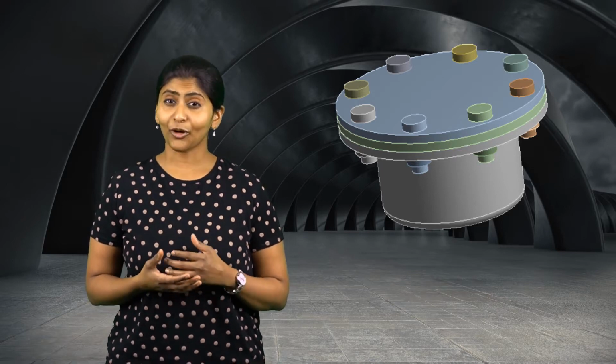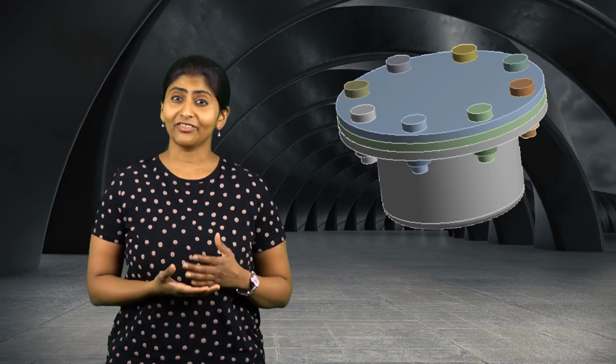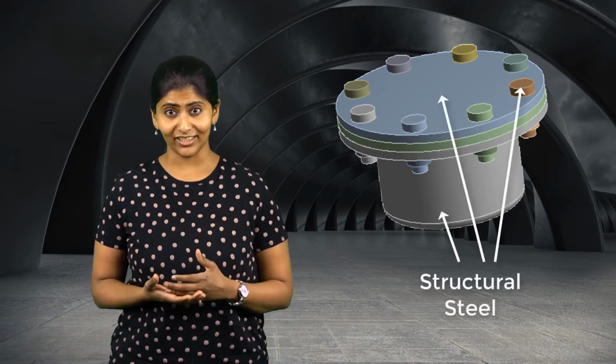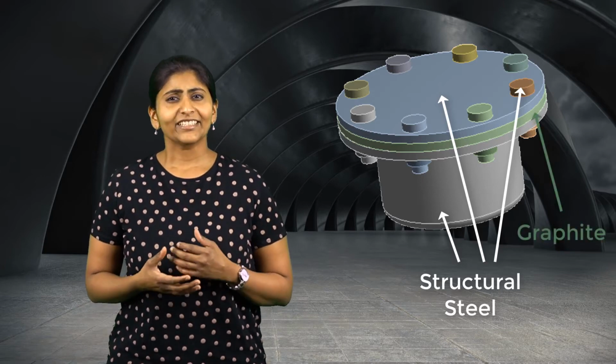Here's the new design. It has 8 bolts of the same dimensions. As you can see, the bolts are modeled as solid bodies with circular heads. The pressure vessel and the fasteners are made of structural steel, and the gasket is made of graphite material. The threads are not of interest, so we simplify the threaded portions and use bonded contacts between the nut and the bolt. We use frictional contacts between all other mating parts.